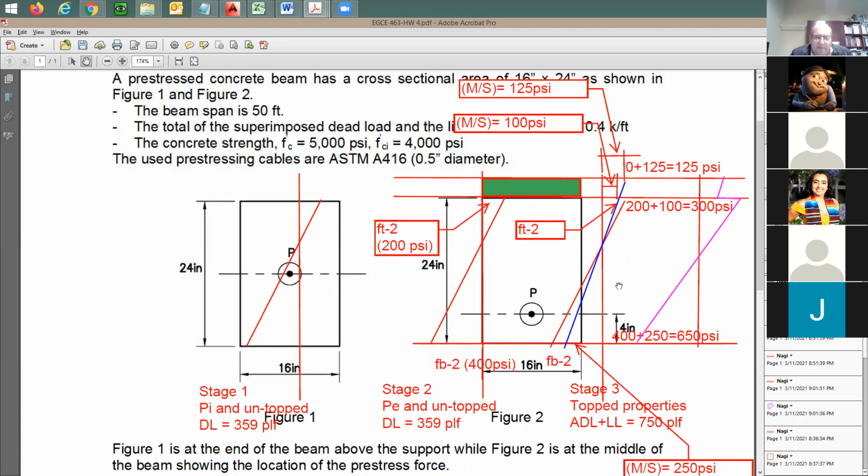No questions. Great. Okay. So stage 2, again, you put the beam in place on the side and you didn't load it with any topping. You didn't do anything to it yet. Now the stress is going to get locked. What does it mean by stress is going to get locked? The stress in this beam is going to stay as is based on the pre-stress force. When you add any topping to it, this topping is not taking this pre-stress force. It will never take it because the beam is already taking this.